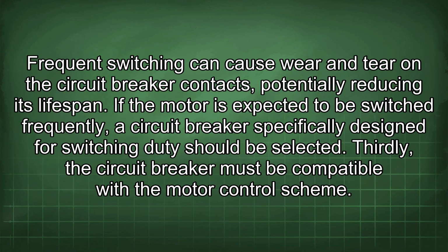Secondly, the circuit breaker must be rated for the intended switching frequency. Frequent switching can cause wear and tear on the circuit breaker contacts, potentially reducing its lifespan. If the motor is expected to be switched frequently, a circuit breaker specifically designed for switching duty should be selected.